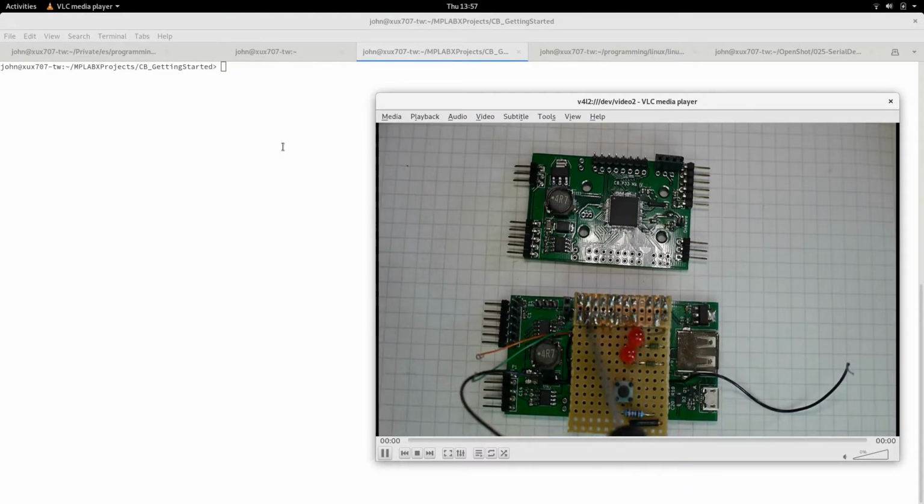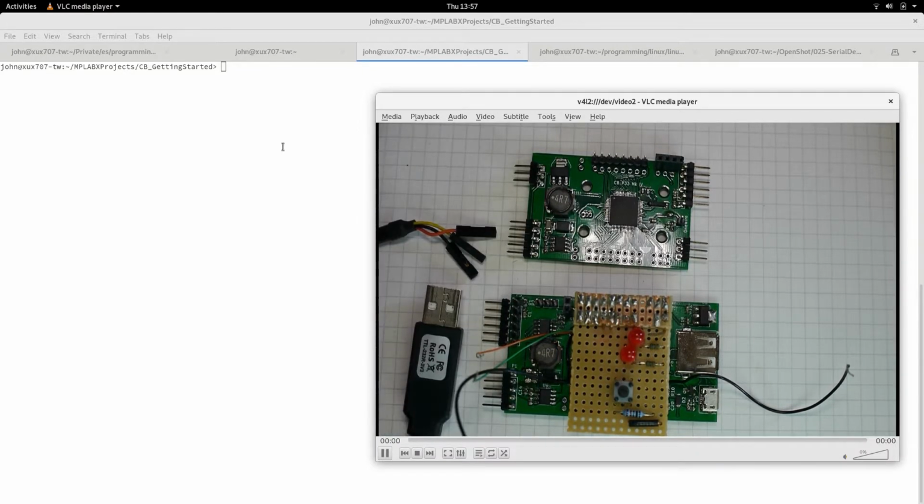The same is true of this board. Ground is on the left as you're looking at it here, and then the other 2 can be receive and transmit, or transmit and receive, depending on what kind of connector you're using. I generally use the FTDI Raspberry Pi, well, they sell it as a Raspberry Pi based serial connector. So all I have is the 3 pins. The black in this case is the ground connection, and yellow is receive, orange is transmit.